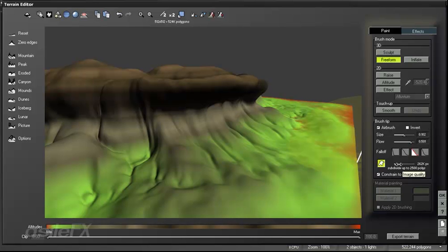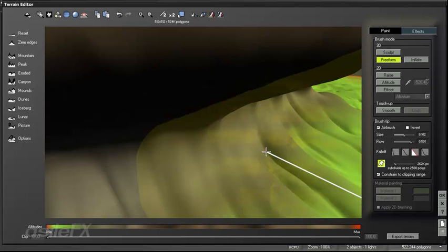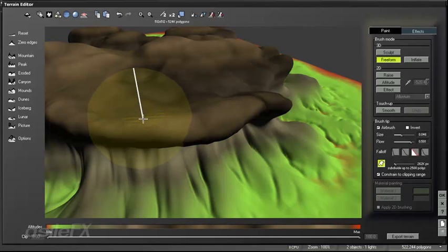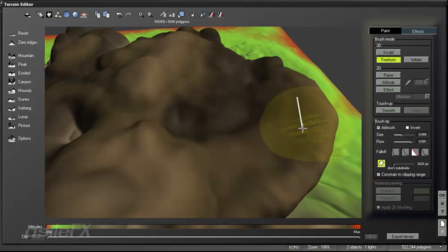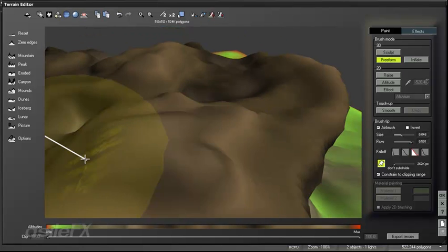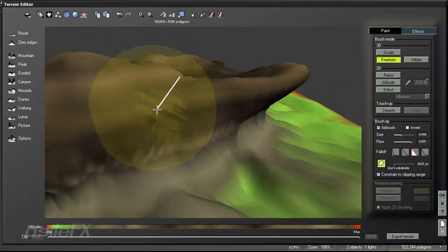and if you take a look, there's a slider right next to where we load in the brush, and what this controls is the subdivision of the displacement layer. You will only see that if you are working with displaced terrain, and you can subdivide up to a certain polygon amount. And you can also choose to reduce it all the way so you're not subdividing anything and just painting normal with it and manipulating the size of the current brush.